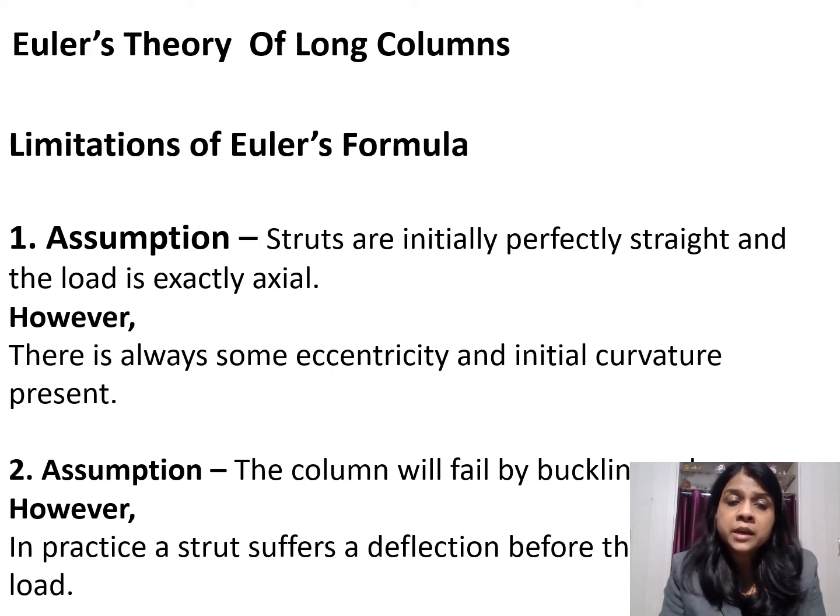Similarly, what is the second limitation? He has assumed that the column will fail by buckling only. But in practical cases, the column will not fail by buckling only. Before buckling, deflection will occur. The column suffers a deflection first before the buckling of the column.